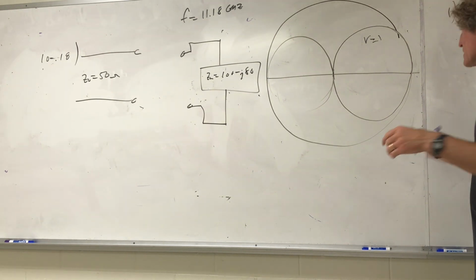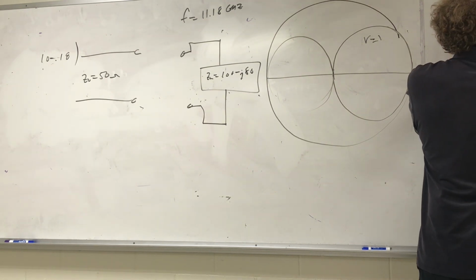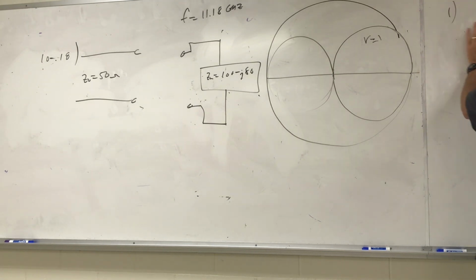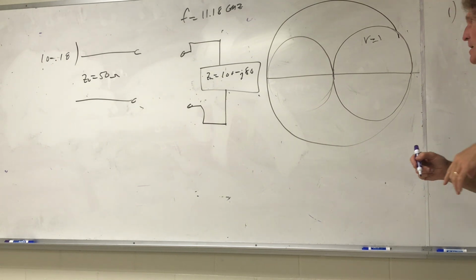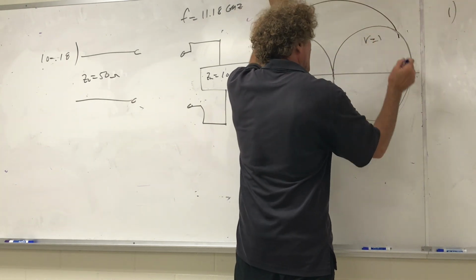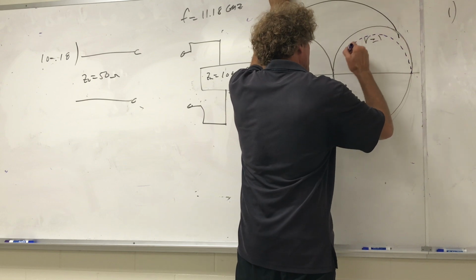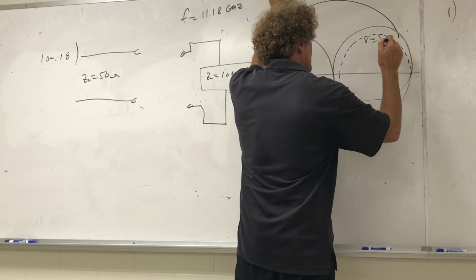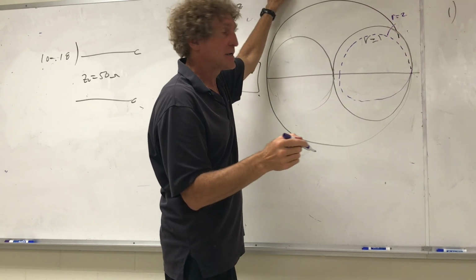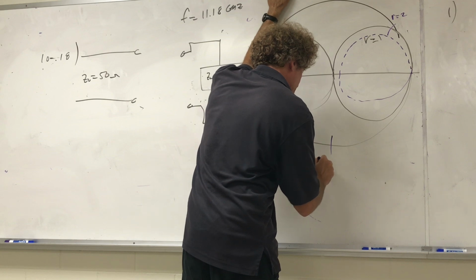Yeah. All right, so little zL is equal to capital ZL over Z naught. And for my case, that's going to be 2 minus j1.6. If you have the Smith chart, please watch this. Make sure you can locate this first thing. If I look at this as R equal 1, 2 would be something like this. This would be the R equal 2 circle right here. You should be able to locate that. And minus j, that's this trajectory here.